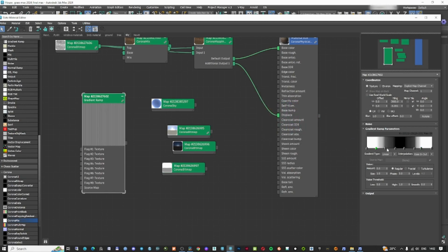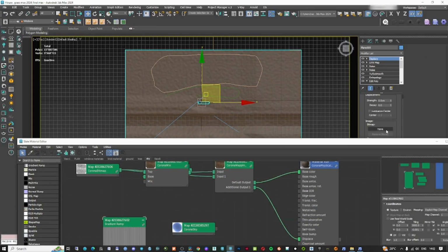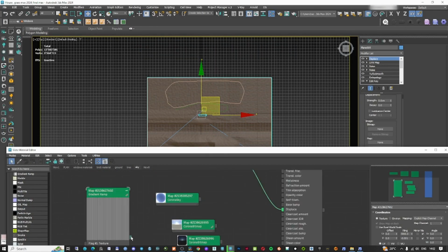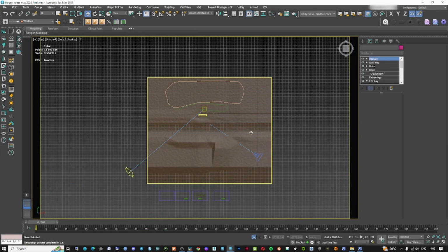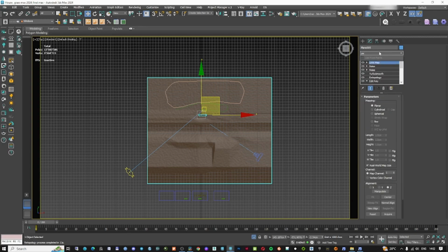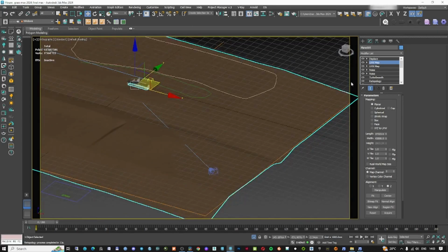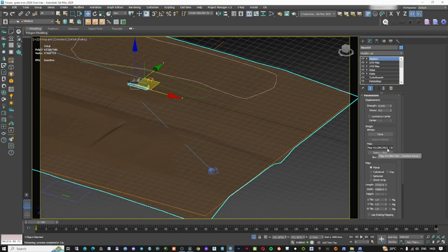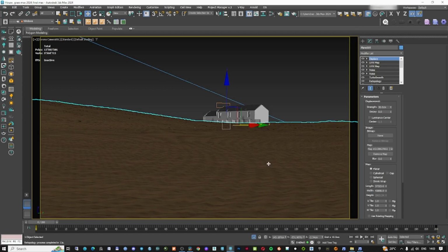After I finish with this, I'm going to apply this texture as a displace on the whole field. Displace is just a modifier coming by default in 3D Studio Max. You can use it for many things. It's very helpful. It wasn't a very good idea to use it on this whole huge area, but I didn't find any other way to actually make it work. I'm just going to use it here in the map field, as you can see. And I'm also going to rotate all of this, so I get all the lines pointing directly to the house.